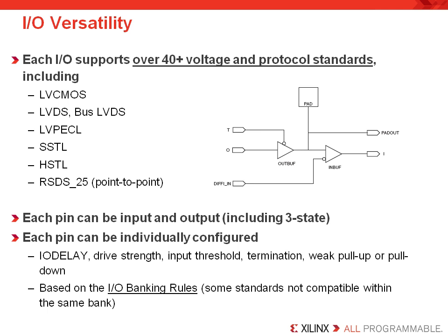Note that there are memory-specific standards of various classes, and differential standards that require 2 I/O pins to receive or transmit signals. The differential signaling standards include LVDS, LVPECL. The single-ended I/O standards include LVCMOS, SSTL, and HSTL. The SelectIO feature allows direct connection of the FPGA pin to external signals of varied voltages and thresholds. This optimizes the speed-noise trade-off and saves you from having to place interface components onto your board. All the dedicated interface logic already exists and can be selected on a pin-by-pin basis.